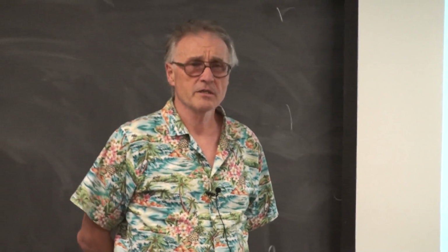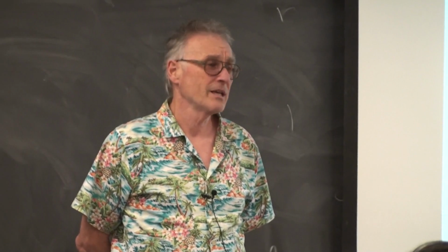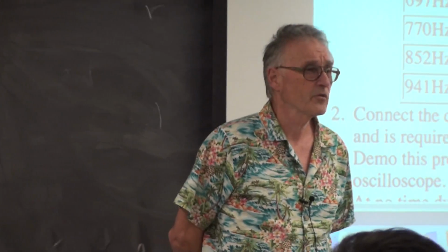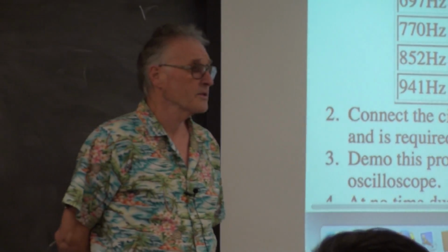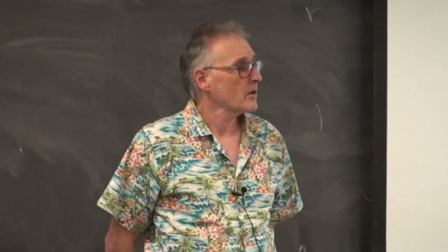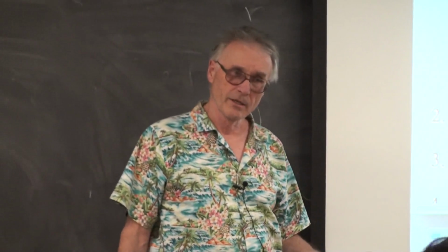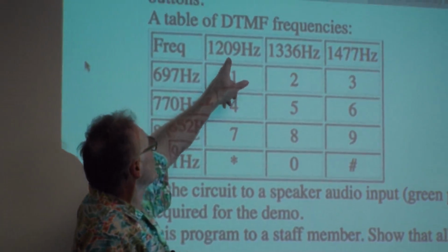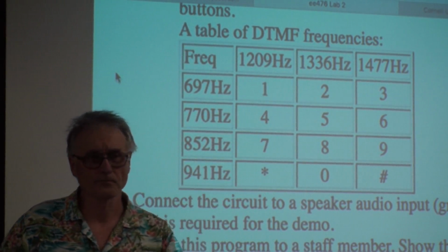That's so your voice doesn't trigger the system, because in the bad old days of analog telephone, the touch tone signals went over the same signal channel as the voice. And so if you could whistle 2 frequencies at the same time, you could dial the phone. Now, the frequencies that are chosen are not harmonically related, so they're fairly hard to whistle at the same time. So 697 and 1209 hertz played simultaneously represents dialing a 1.